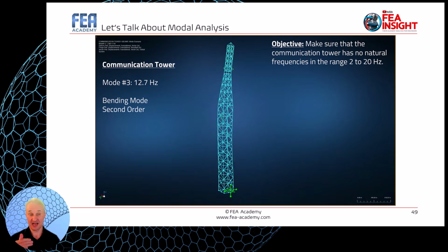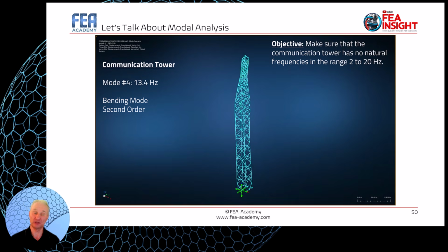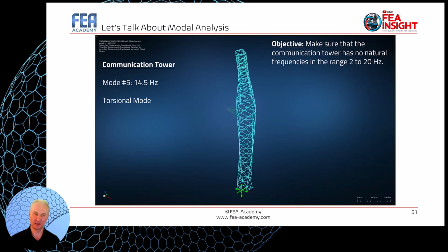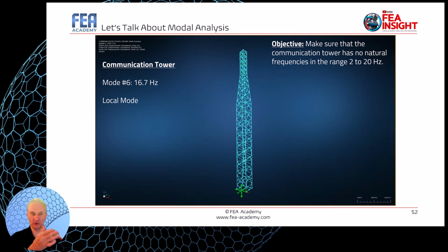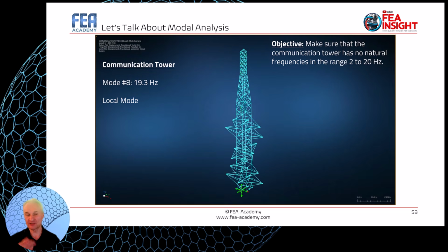And then I can implement that into the model and rerun the numerical simulation to see how the natural frequencies are shifted, in order to go outside of this critical range, the vortex wind range, with a certain margin of safety, let's say 10 to 20% of margin of safety.